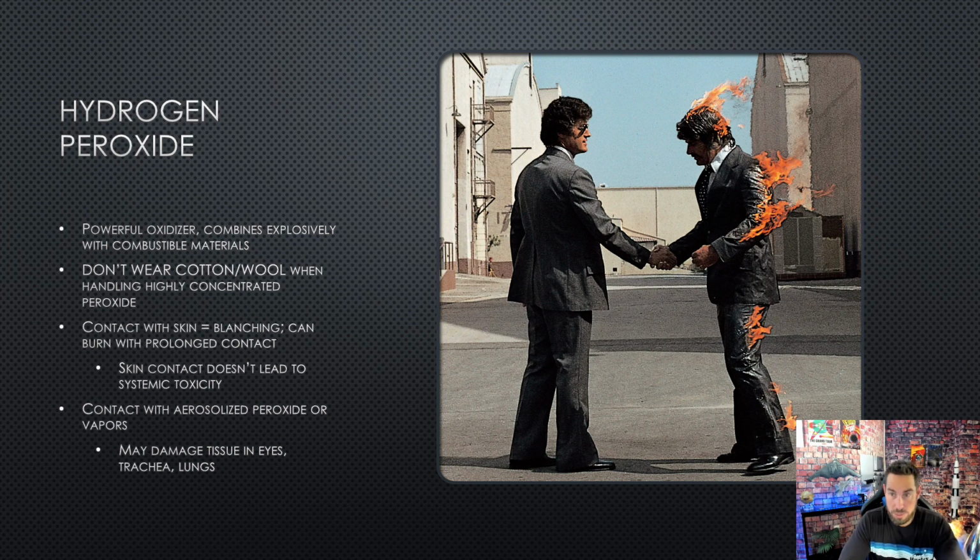Peroxide is a super powerful oxidizer, but it combines explosively with combustible materials. Just like I was talking about with liquid oxygen, don't wear cotton or wool if you're using highly concentrated peroxide. When you get up into the 98% peroxides, if you're wearing wool or cotton, you may spontaneously combust. So I would avoid that.